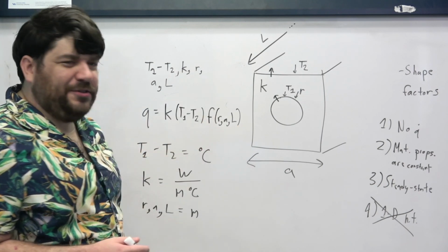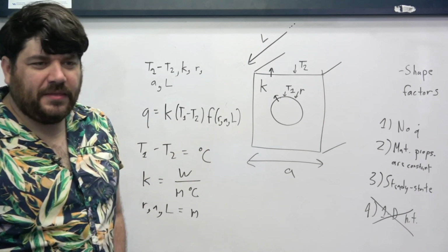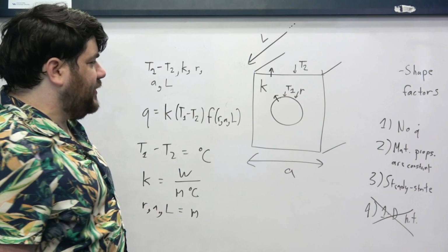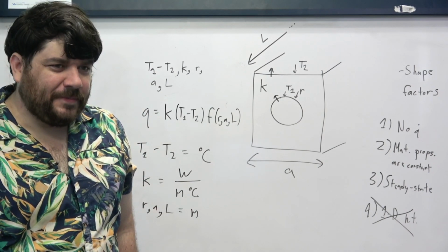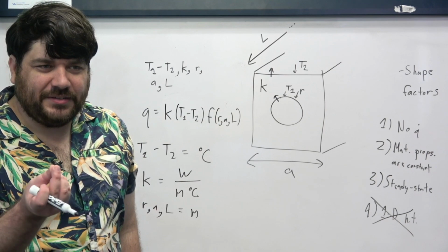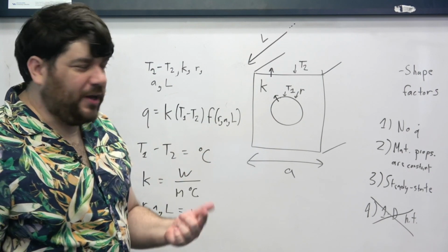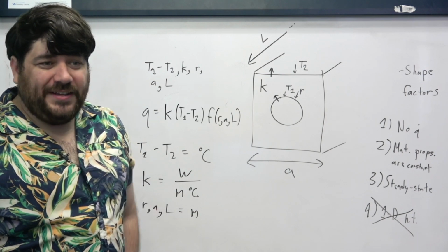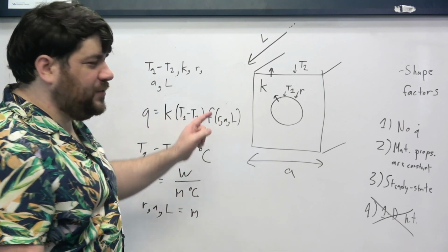So how do we try to find F? That's a good question. And the way that we usually find what this function is, is via either doing numerical simulations of systems like these or by doing experiments. But the interesting fact about this is that we've converted this problem from being something where we didn't know at all what this heat transfer function was into a problem where now we know the dependence on the thermal conductivity and the temperature difference. We just have to find what this geometric function is, which is only a function of the parameters that describe the shape of the system, right? And we also know that this function, whatever it is, has to have units of meters, right? Because it's the only way that this is dimensionally compatible, that the stuff on the left has the same dimensions as the stuff on the right.